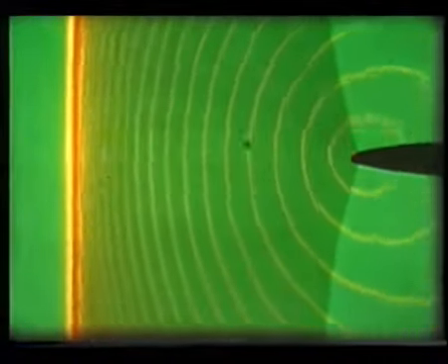As before, the supersonic regions are lighter green. Like the shock waves on the wing, the bow wave is formed by the constant piling up of pressure waves, this time from points near the leading edge inside the subsonic region. As speed increases, the bow wave comes in quickly towards the leading edge, but there's still a subsonic region in between. A shock wave oblique to the airflow usually has supersonic flow on both sides of it. A normal shock, one perpendicular to the airflow, always has subsonic flow behind it.